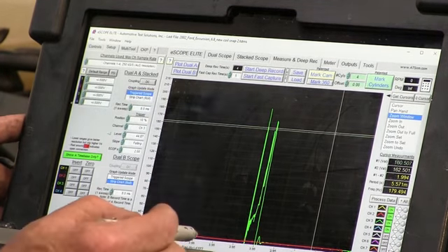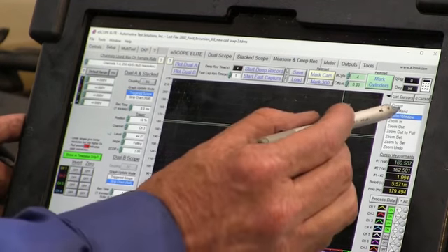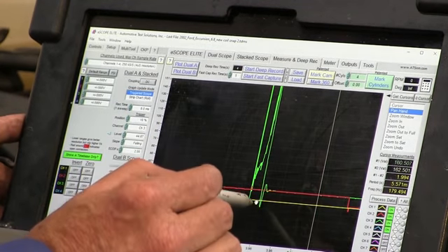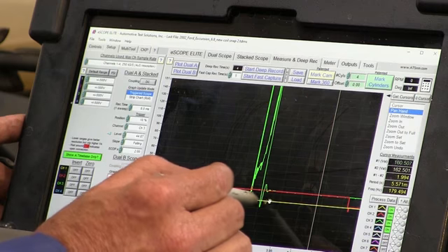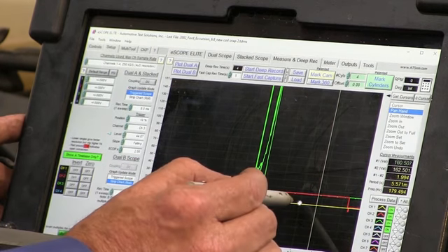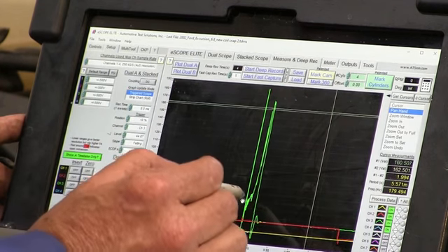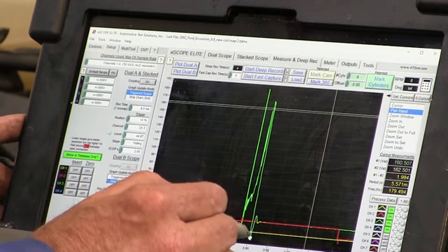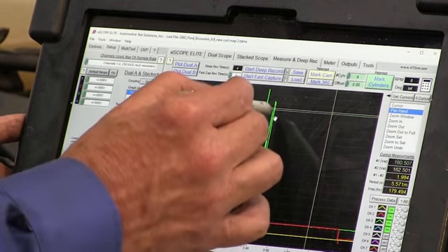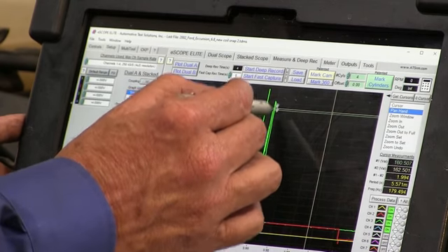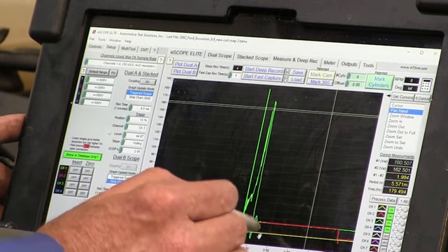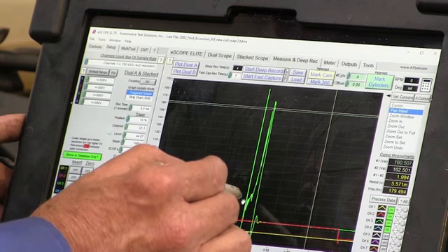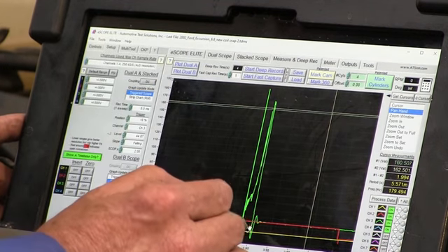That's a lean cylinder. And I know it went across the plug because look at the tail. Do you see how deep the tail went? It went across the bottom plane for the sensor. It had so much problem discharging the energy because it's so lean that I couldn't get rid of all the energy, the reserve capacity in the coil, so the coil has to reabsorb it. That's the negative going tail. So this is really having a hard time to discharge.